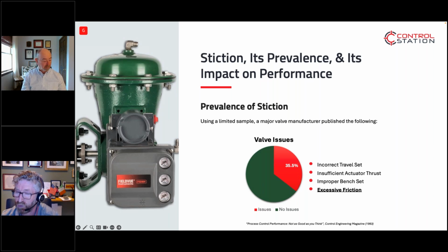Undersize and oversize can also feed into stiction. Overuse and underuse of valves can cause the same stiction issues to increase. So it's defining each valve's performance and then getting a program to manage that until you can get to a shutdown, or until you're upsizing your plant next year and you can use that opportunity as a time to put in the more appropriate system for it. You know, it's going to be key to it.